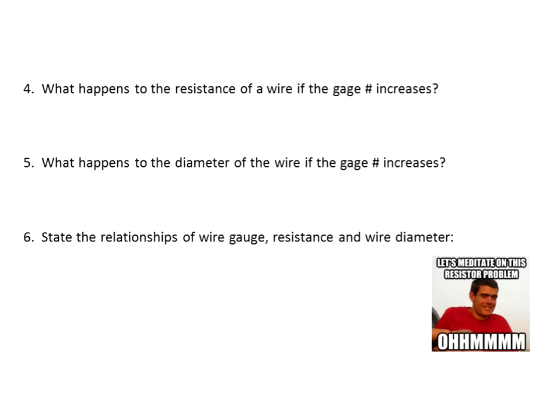All right. Now, I believe that there's a handout in there about wire gauge. If not, you can pull it up on the internet about wire gauge and resistance and size. And the American wire gauge tells us the thickness of the wire. And the odd thing about the American wire gauge is that the gauge number, or the AWG, has a number to it. And if the gauge number is bigger, the diameter of the wire is going to be smaller. So the diameter goes smaller.